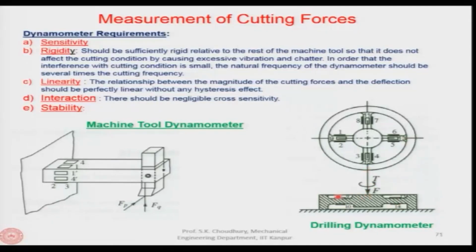So, if you apply the torque, these 9, 10, 13, 14 and all others up to 16, from 9 to 16 will be affected, and the torque can be measured equivalent to the deformation of those strain gauges in these cases.